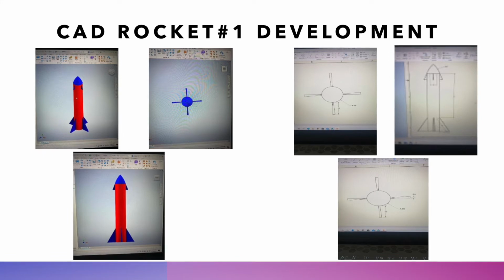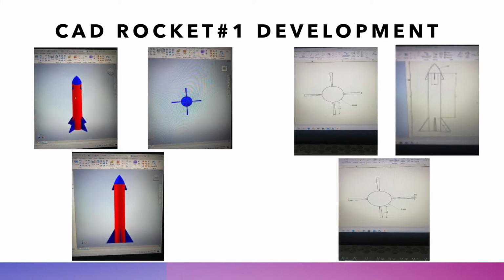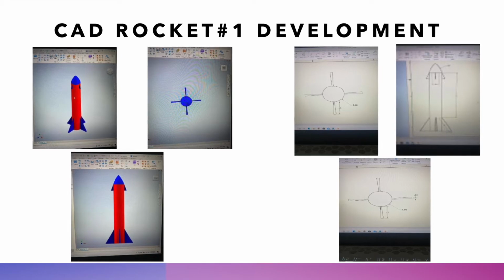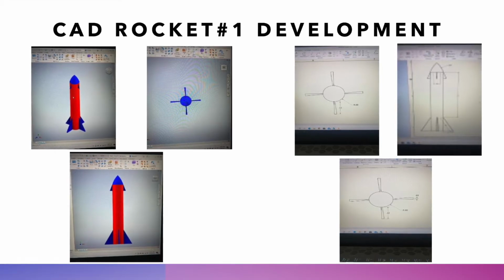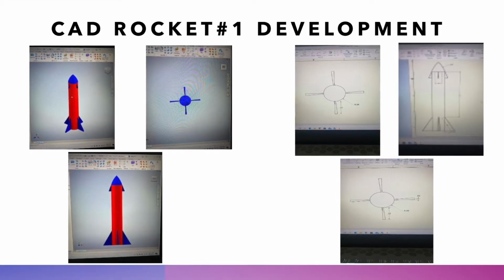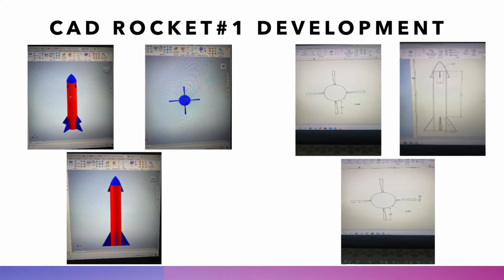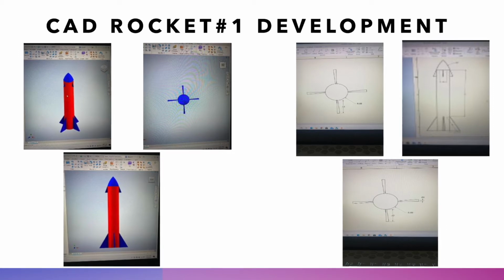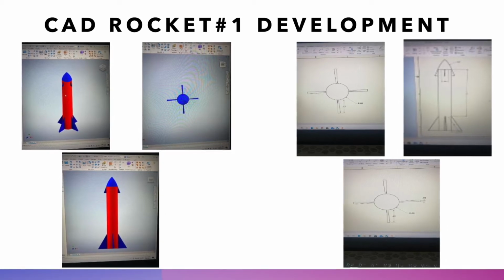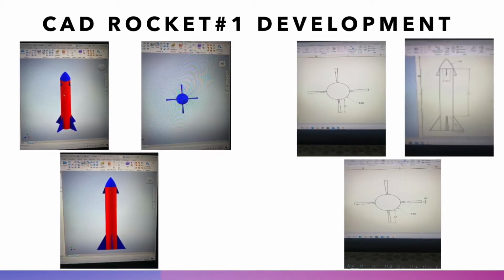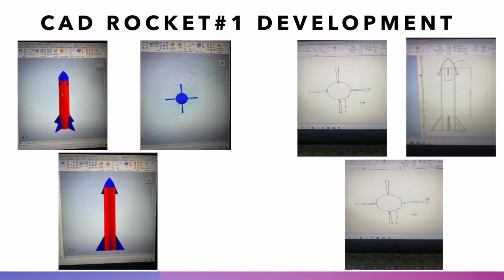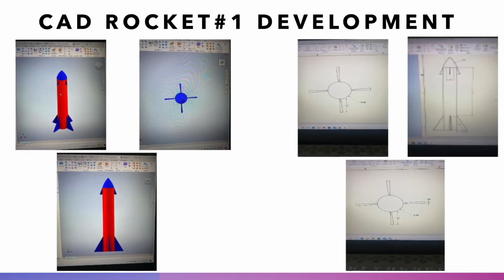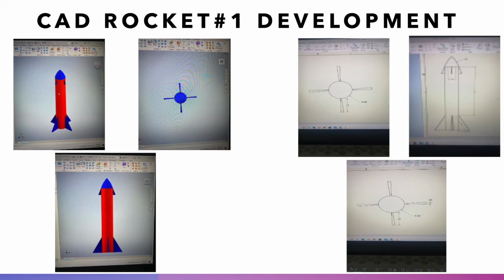4. Click on the Revolve option again, where the body of the rocket and its tip will be selected. 5. Look for the body of the rocket, which is a rectangle. Select the Project Geometry option so that the figure can no longer be seen in 2D, and click the Line option below to create the middle rocket fins from below the middle of the body to its base. To finish, select the Finish option again. 6. Repeat step 5 three more times on each side of the rocket.